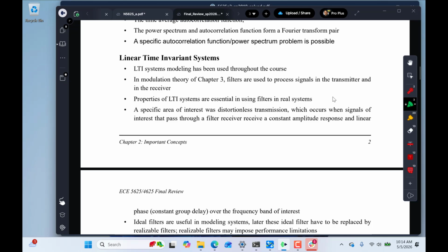You know that the filter will ideally have zero insertion loss, and will have no group delay, but if a filter has some group delay, then like in Project 1, we compensated for it by putting, say, in the Hilbert filter, remember, we put a delay in there to compensate.